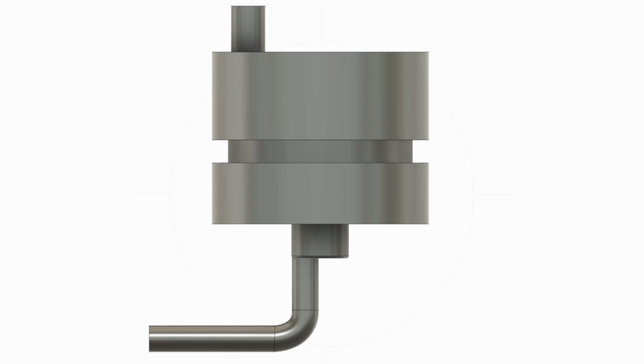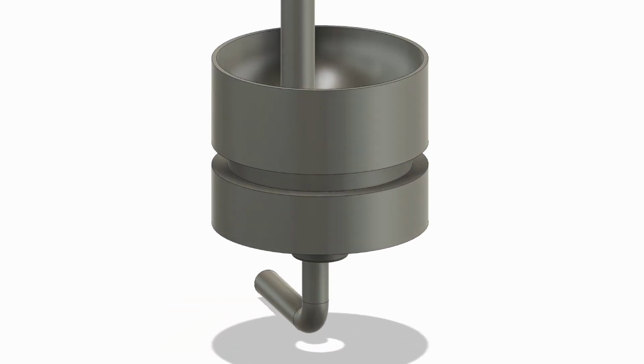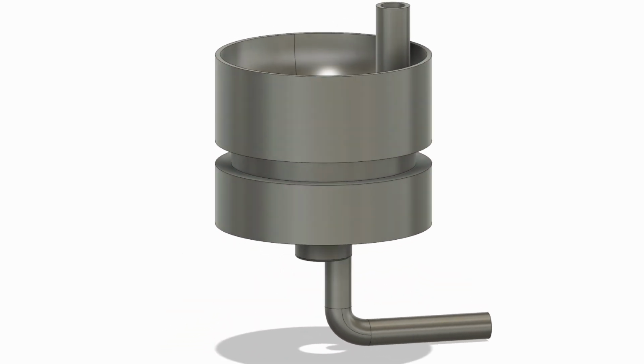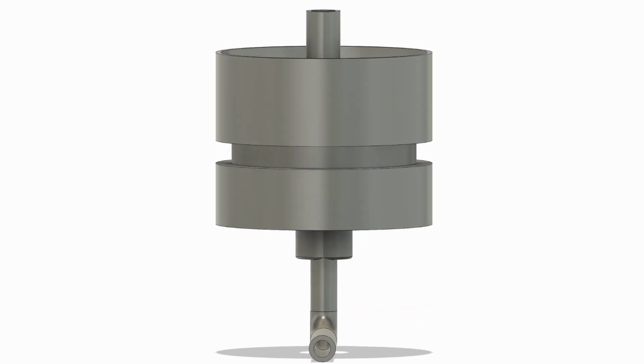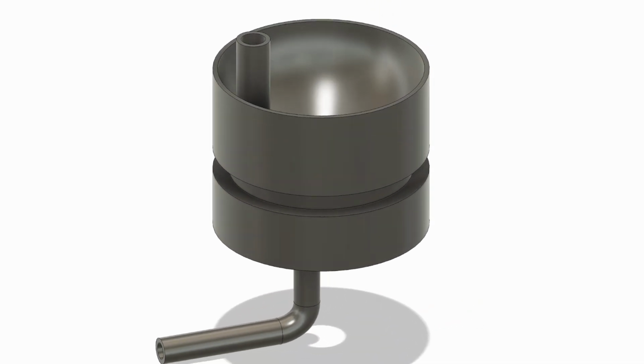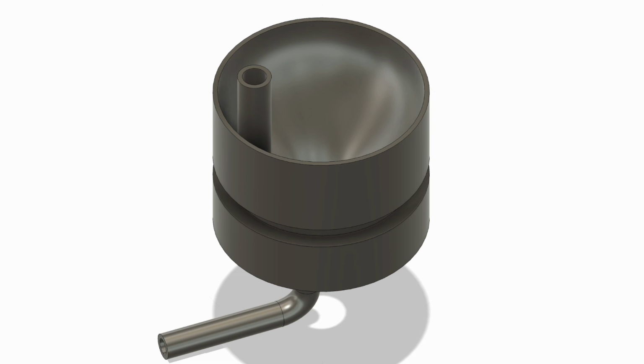The generated transfer function was exported to Fusion 360 computer-aided design software to create the axisymmetric nozzle shape. Additionally, a groove was implemented in order to use an O-ring, preventing possible leaks. A critical element of our design is the pipe for pressure equalization, which will reach out of the cap at the edge of the outlet hole.